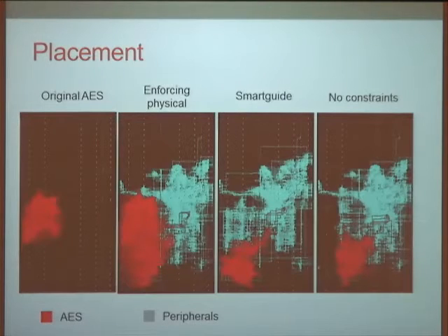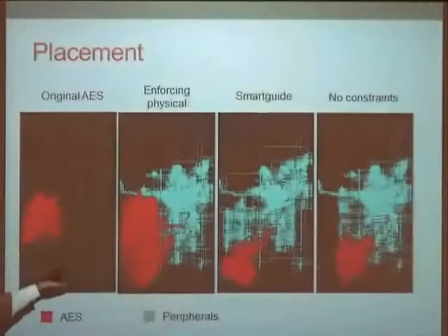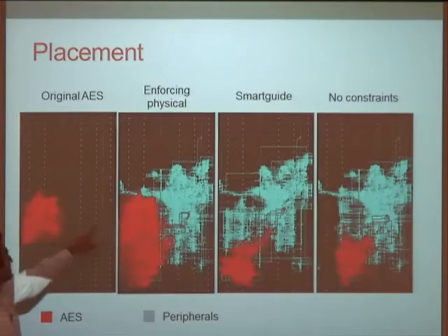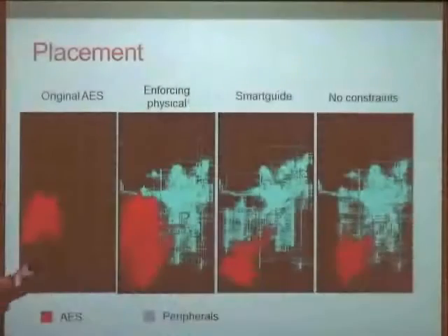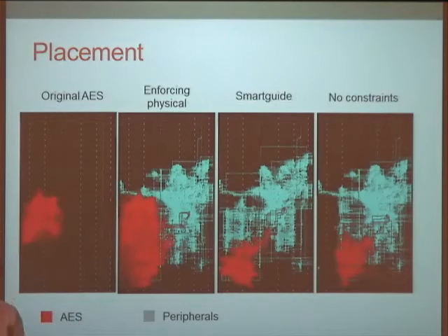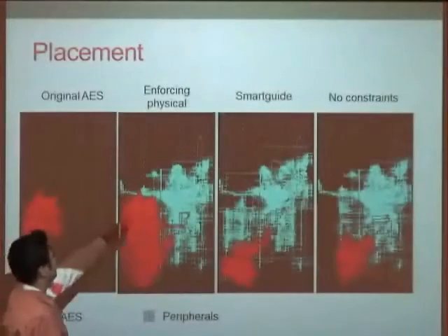So the problem is that whenever you re-implement and re-synthesize your design, the names of the components might change. The tool has a random number generator that, for certain memory components, assigns a new name every time you recompile. So the names of certain components change, and I tell the tool, okay, lock this component at this location, and the tool tells me there is no such component. So if you see, these components are being locked because their names haven't changed. But the ones whose names have changed are not locked down, and they're placed scattered all around the place.